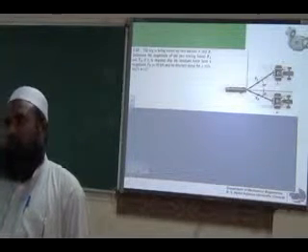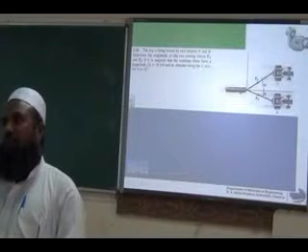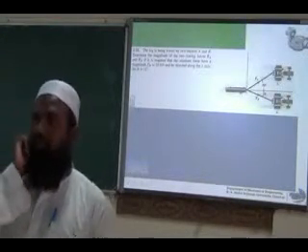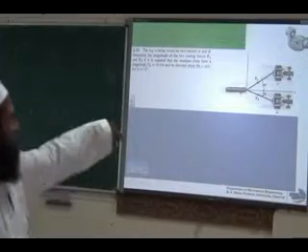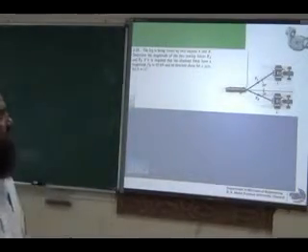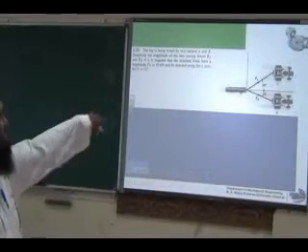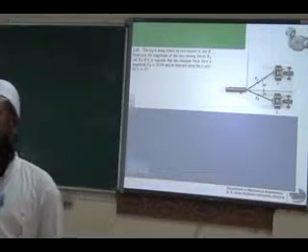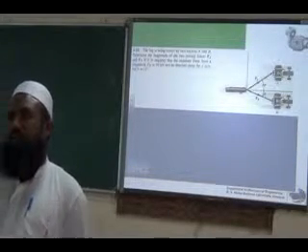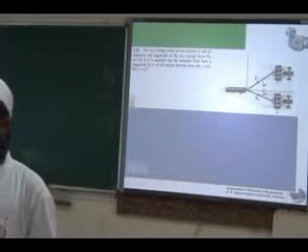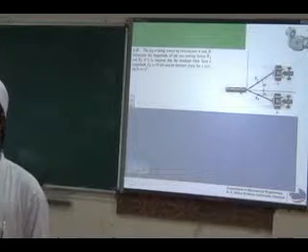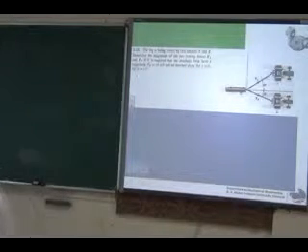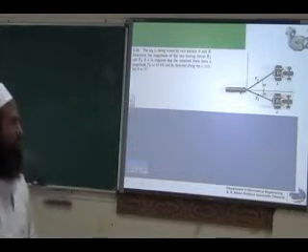So you draw the parallelogram. Find the unknown angles. The angles included in the parallelogram will add to 360 degrees. Opposite angles are the same. So at this corner, the tails of the two forces make 45 degrees, 30 plus 15, 45 degrees. So the opposite corner will also have 45 degrees. So 360 minus 90 will be the remaining angle. You divide it into 2 and put it in the diagonally opposite corner. So we got all the angles. Now we can apply the sine rule to get the unknown forces. So draw the parallelogram.